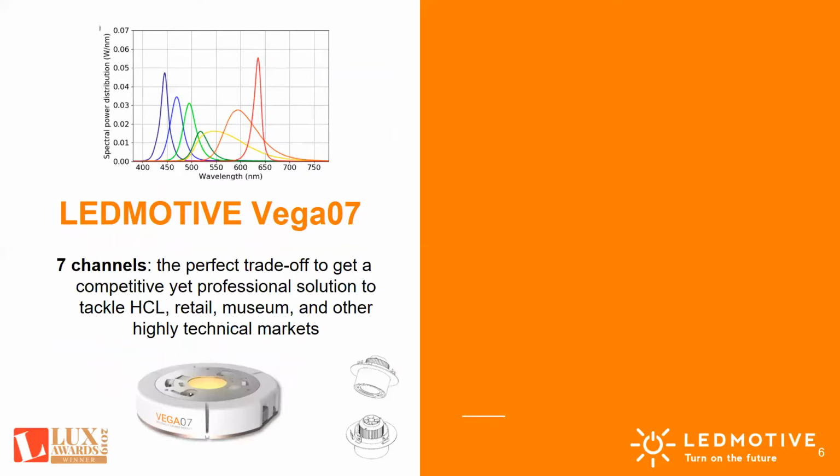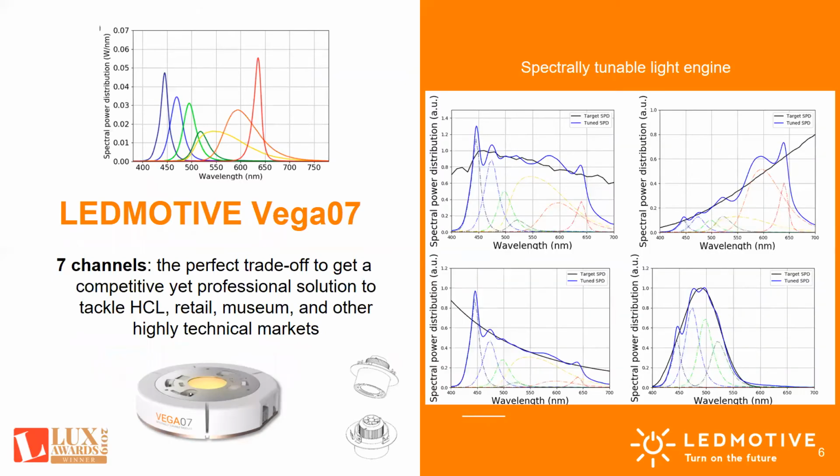And one example of a spectrally tunable lighting system is the Vigo 7, that is a small light engine designed and developed by Ledmotive that has 7 different channels and is easy to integrate into more complex optics like downlighters or projectors. By tuning the amplitudes of these 7 different channels, we can design different spectral shapes and match any possible light.